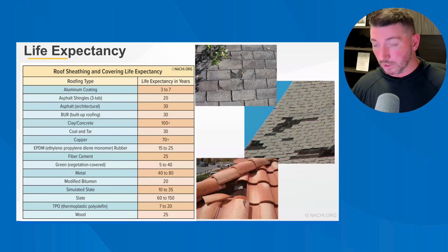At our company, we perform desaturation tests to take the asphalt off of a shingle using mineral spirits. And there's a couple other chemicals that can accomplish that. So, nearby industrial facilities, if they're releasing chemicals into the air, that can degrade the roof surface. And the orientation of a roof can definitely have a significant influence on the long-term condition of the roof.